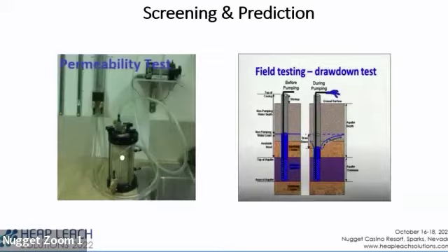So lab permeability tests are really, I was going to say cheap, that's not quite true, but they're abundantly available, not unreasonably priced. Lots of mines build these apparatuses on site, so you can get lots of cheap data quick. In situ testing is vastly better, but substantially harder to pull off. So we don't do that very often.